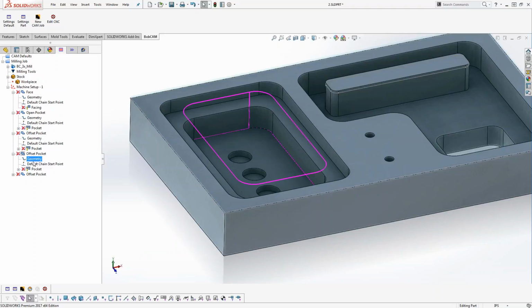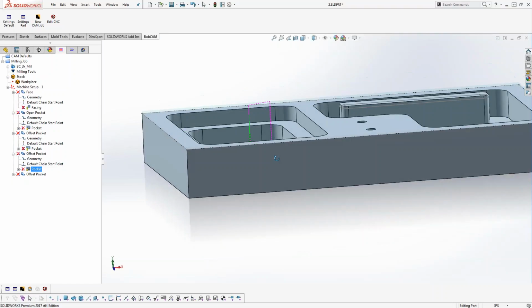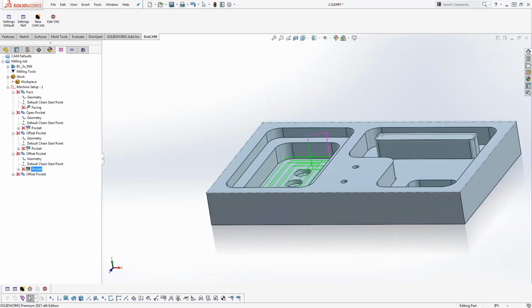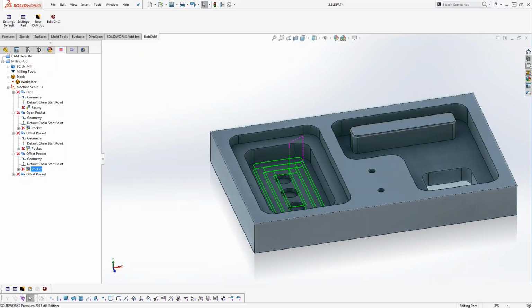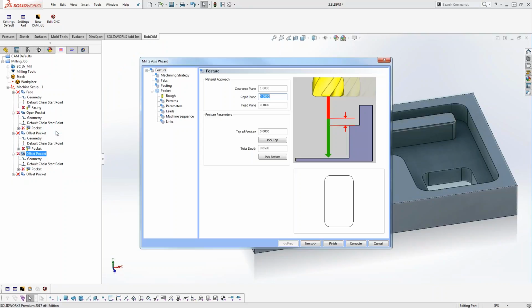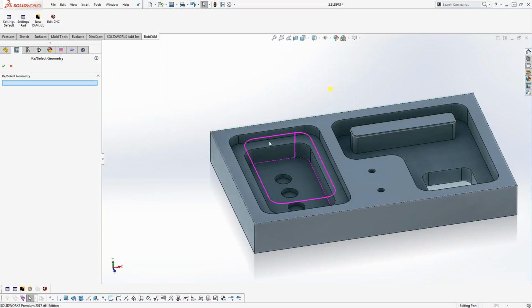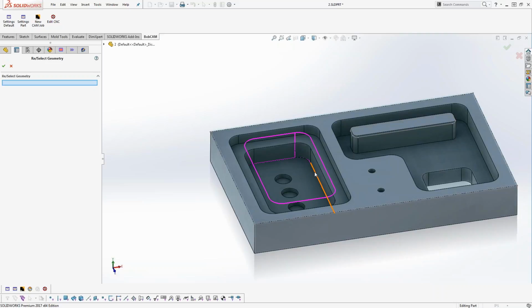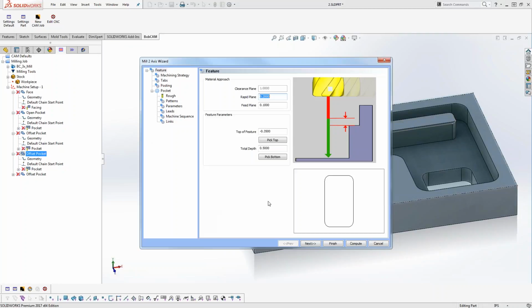If we go ahead and compute this here, we are going to see that we get 2 passes. This is one way to do this. I generally wouldn't try to fake the settings or do the math for it. What I would do in this example is tell it where I'm going to start cutting, which would be this inside pocket level, and then pick the bottom, how deep it's going to go. So it adjusts where it starts cutting from and where it ends cutting.